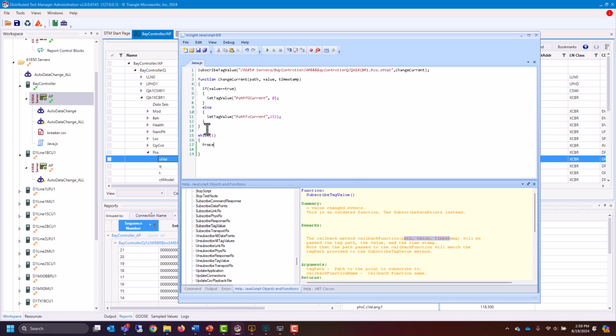And then you'll want something called process script events, which is basically a fancy wait that allows you to just sit there in that forever loop, not consuming all of your cycles, but it is basically waiting for that data change to happen at any point. So those are the top 4 different ways that you can change data inside of a server. All of this has been for 61850, but also applies to DNP3, 101, 104, Modbus, all the other protocols as well.